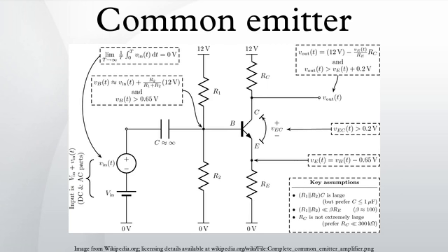When an AC signal is applied to the transistor amplifier, it causes the base voltage VB to fluctuate in value with the AC signal. The positive half of the applied signal will cause an increase in the value of VB. This in turn will increase the base current IB and cause a corresponding increase in emitter current IE and collector current IC. As a result, the collector-emitter voltage will be reduced because of the increased voltage drop across RL. The negative alternation of an AC signal will cause a decrease in IB. This action then causes a corresponding decrease in IE through RL. The output signal of a common emitter amplifier is therefore 180 degrees out of phase with the input signal.